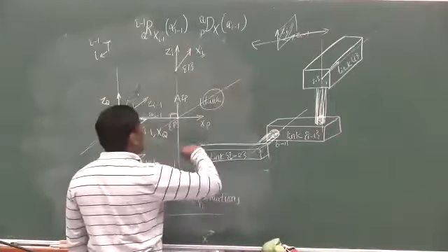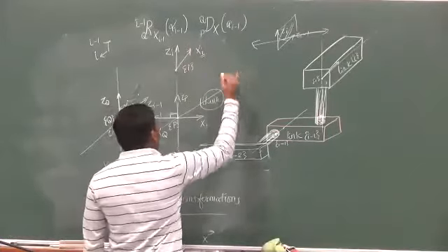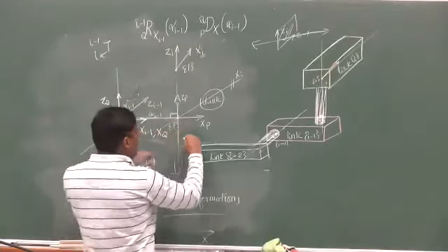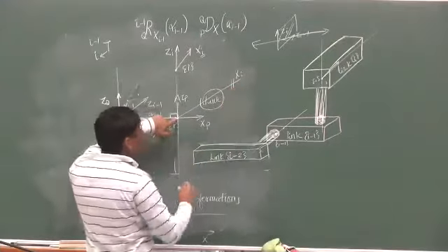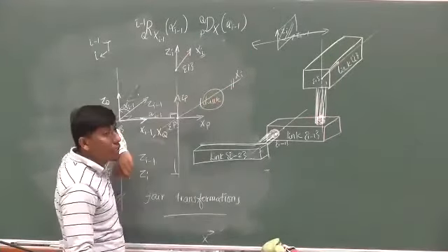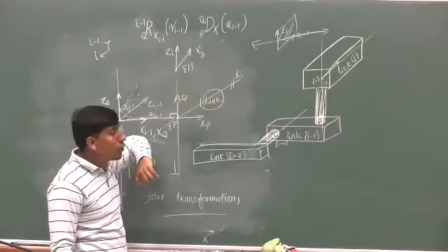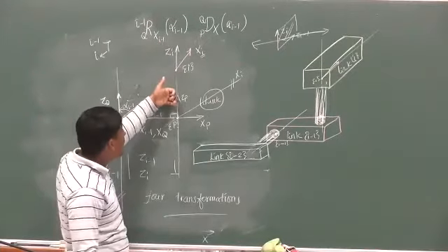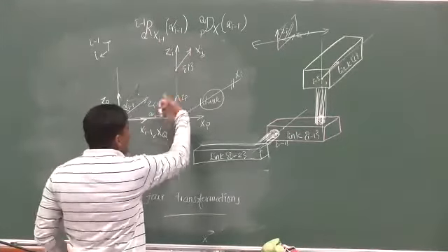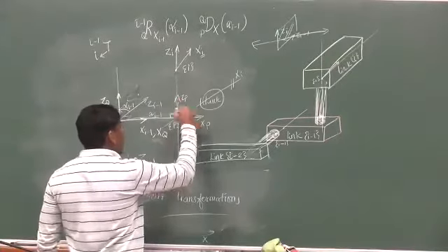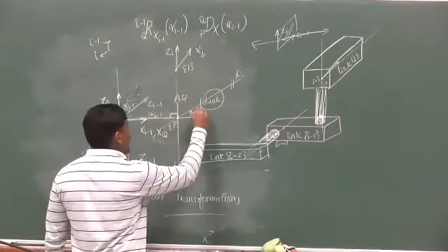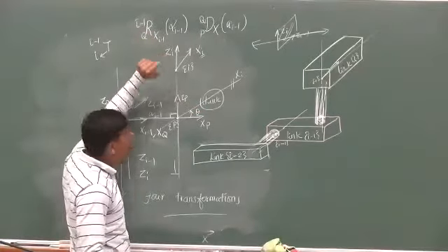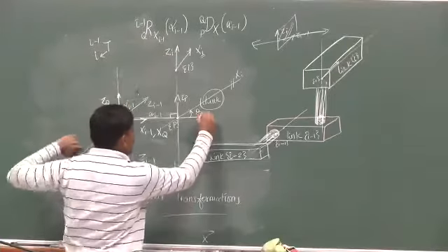I am drawing a line parallel to xi at the point P, or frame P. Now this is parallel to xi, and you can see that xp and xi are oriented apart. Which axis can we use for rotation? You can easily see, right? This is about the z axis. I am taking the z axis with the right hand rule, which says this is the positive rotation. So now I rotated this by theta degrees, about zi, so it is called theta I.